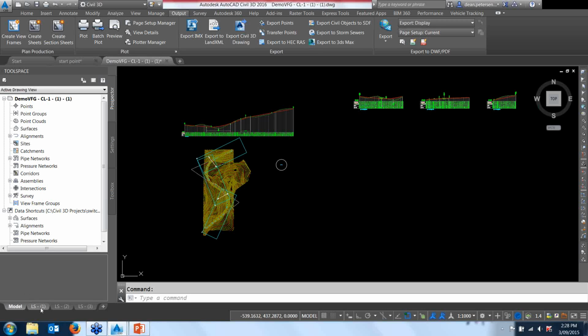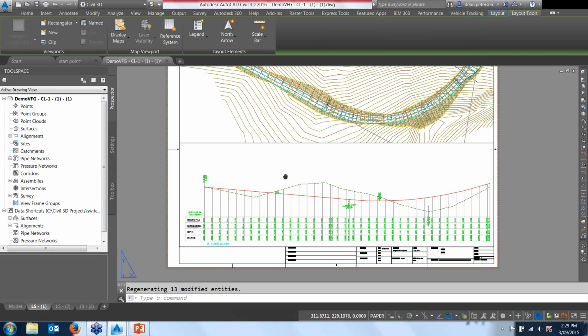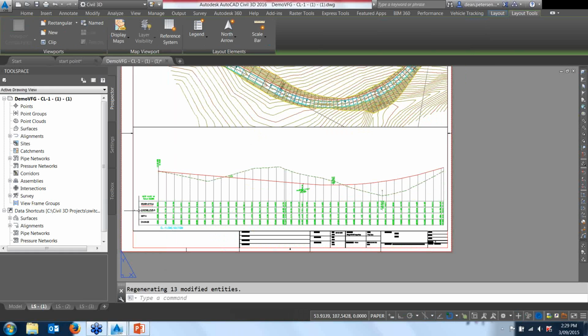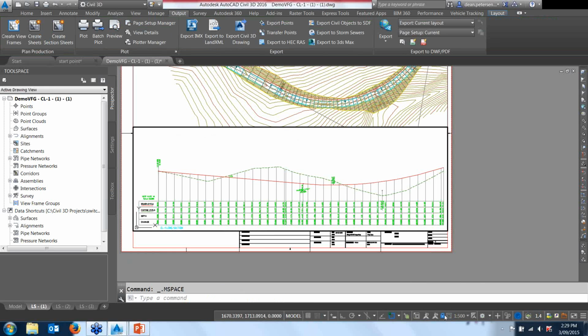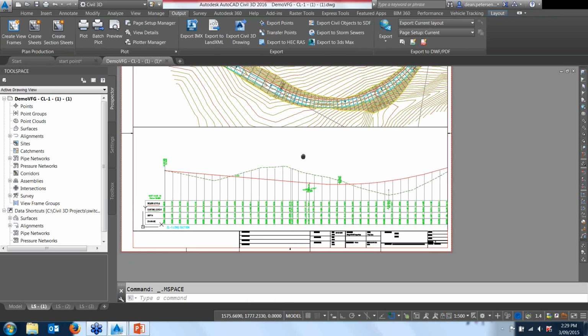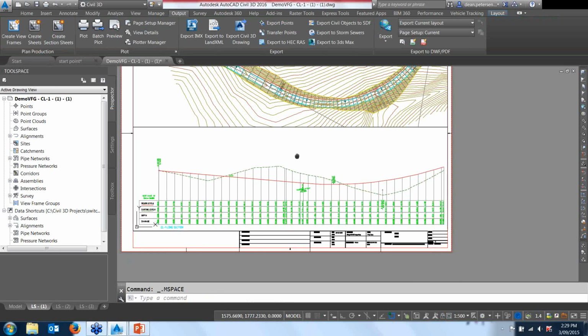Sometimes I should say in these long sections you may find that these band titles are a little bit off the sheet, so you may need to come in and give a little adjustment by making that viewport active, unlock it a bit, and just move it horizontally left or right. As I've aligned these on the center, they're not doing too bad a job, so that's working okay. And always remember to lock it again, of course.